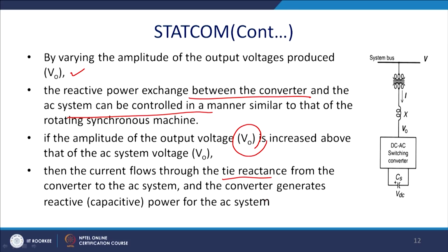This is the principal operation, and for this reason this voltage is required to be higher than the rectified DC voltage. Generally it will be 30% higher, depending on how much you are going to compensate.